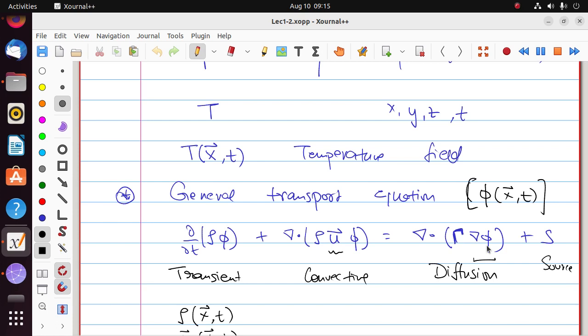You may have learned about it in your other courses where you have written the equations for fluid mechanics or heat transfer. And the last term on the right hand side is called the source term, which is responsible for creating something. Let's say if you're talking about the energy equation where you have heat, it could be some electrical element in some place in the room that is generating some heat. That's a source term, because that's neither convection nor conduction. In fact, anything that is not a part of these three is usually put in the source term, mathematically speaking. You can do that.